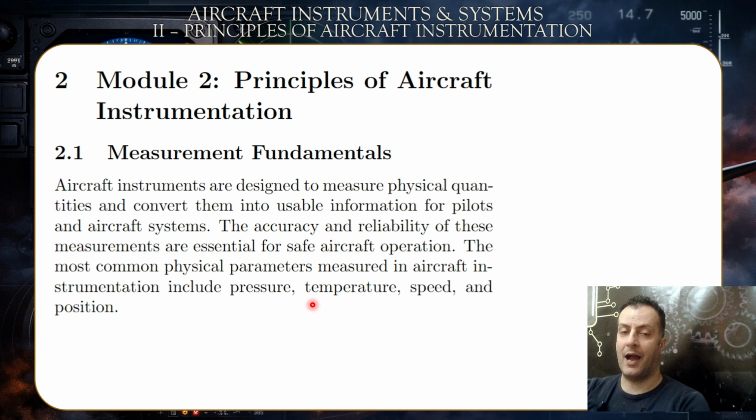So the altimeter converts the pressure differential between the pressure from the outside and the static pressure, which is the air that has been kept and sealed when the airplane was still on the ground before flying into a specific altitude. So the difference between that static air, which is the pressure at ground level, and the dynamic air during flight, that differential can get us to calculate the altitude, the VSI, during movement of the air,